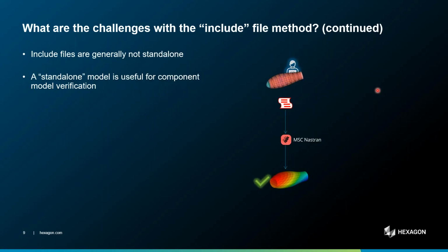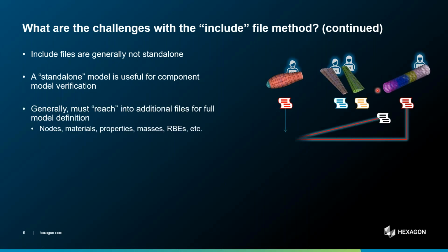And then another challenge with the include file method, and it's going to be the last one that I illustrate, but you may have other challenges that you are aware of, is that include files are generally not standalone. And a standalone model is really useful for component model verification. Is my model really all connected together? Is its response kind of what I expect? Because it's easier to debug it now than to try to debug it once it's included with the rest of the structure.